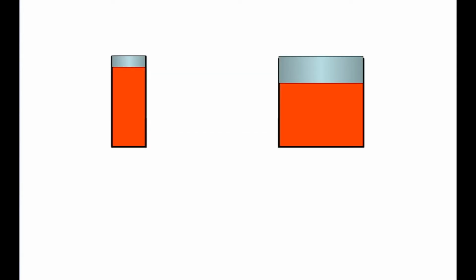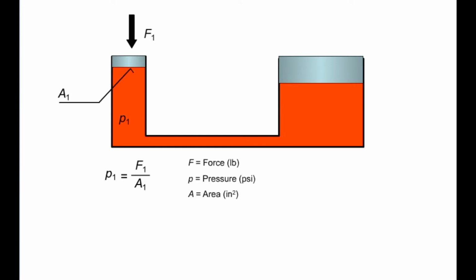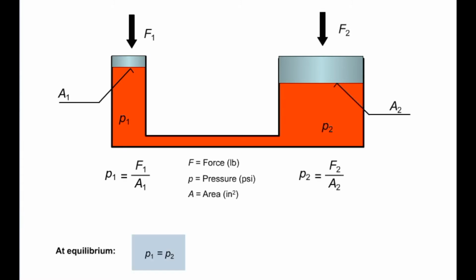Since the pressure is distributed equally in all directions, the shape of the container isn't important. In the same way, if we took two such containers and combined them together, the same pressure would still act throughout. Let's look at what conclusions can be drawn from the above. A force F1 acting on surface area A1 generates a pressure P1. Pressure P1 acts equally at every point throughout the system, including surface area A2.